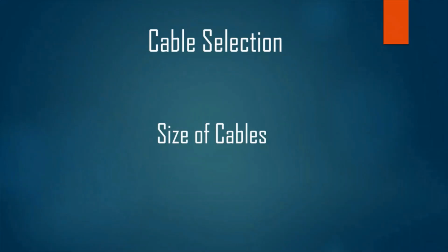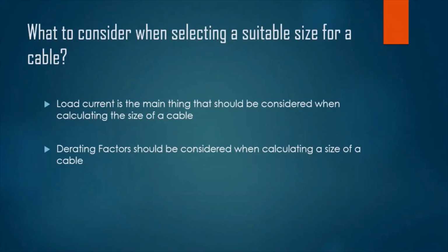Hello everyone. In this video, we will see how we can select a suitable size of a cable for our project. In the beginning, let's understand what to consider when selecting and calculating the size of a cable. Well, we have to consider two major things. First is the load current, and second is the derating factors.